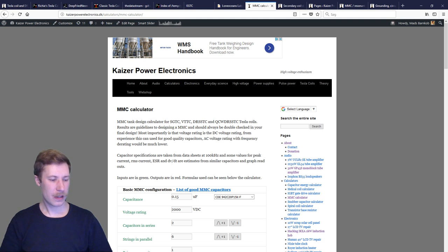Okay, Falk asks, do you know of anyone using SMD MLCCs for the MMC? Is it feasible? Now I have not looked too much into doing something with SMD capacitors, but I do know that the MLCC capacitors are very susceptible to temperature damages. Micro-cracking inside the capacitor is often a failure mode seen in electronics today.